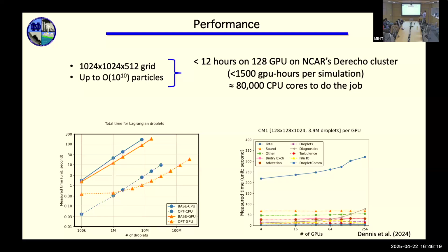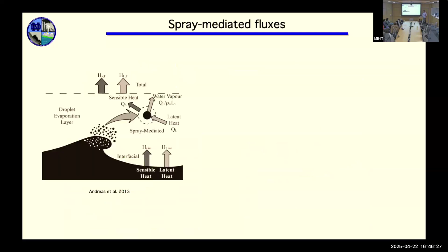But it's fast and efficient, because especially the droplet solver, the GPU can just rip through it really efficiently, because the droplets don't talk to each other. But the two-way coupling doesn't work that way. You do have to compute and send back the coupling force. So it's sequential, right? It's got to do the flow solver and then wait for the droplet solver to send it back. There are tricks you can play there, which we haven't explored.